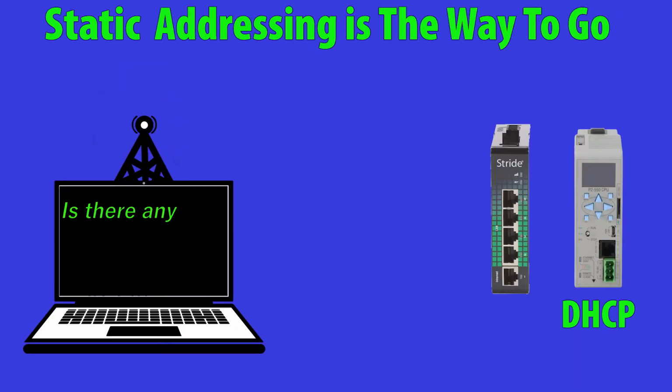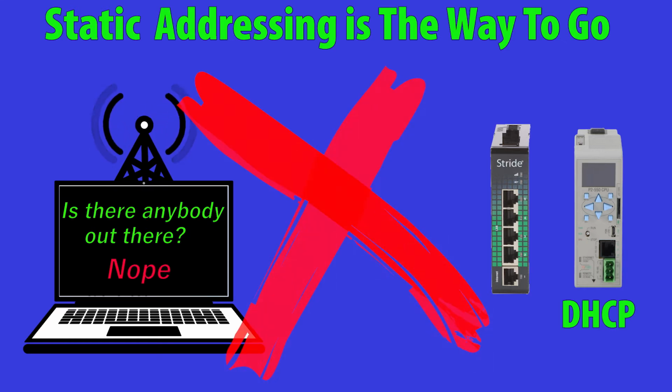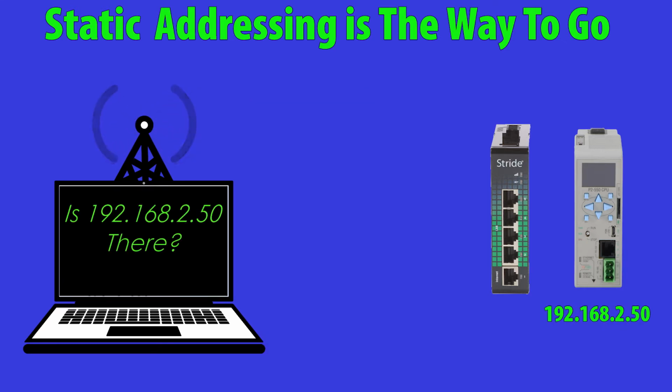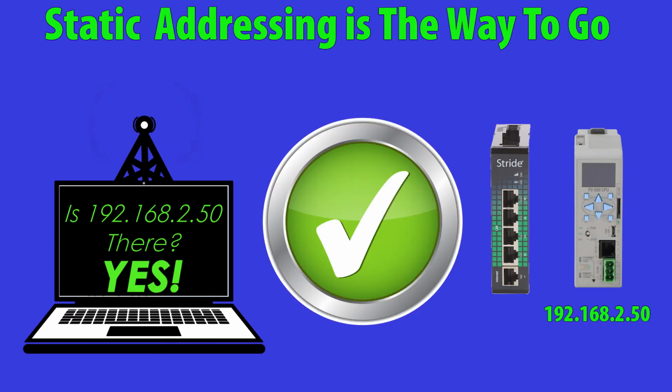It is very important that everything is a static IP address, as one limitation of VPN networks is that broadcast comms will not work, and broadcast comms is what's used for auto-discovery of devices.